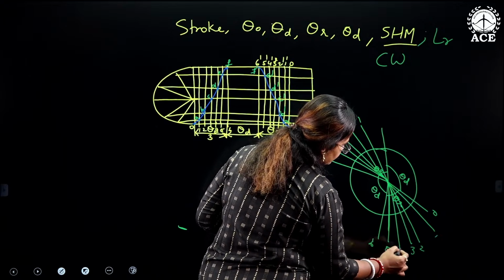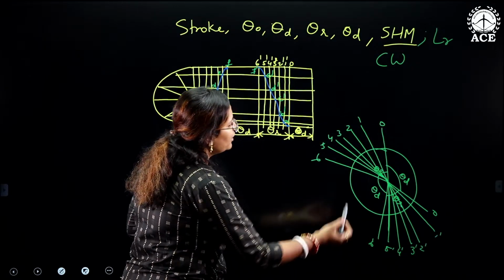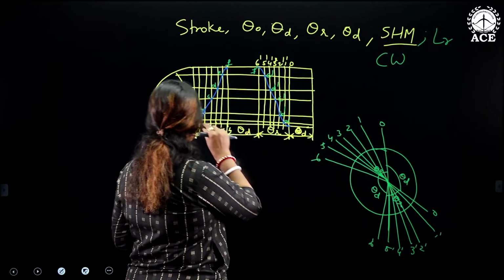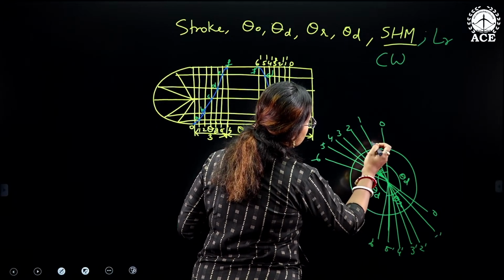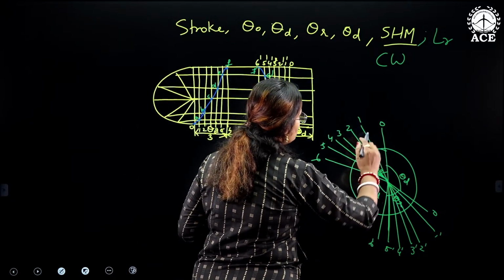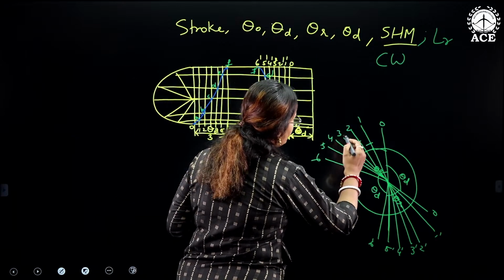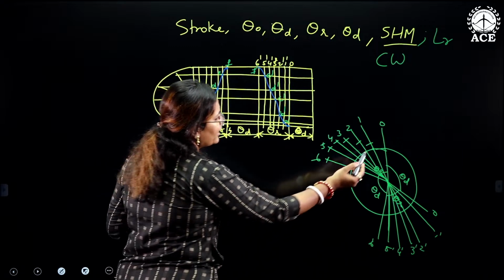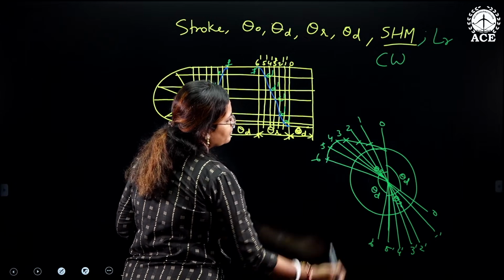So from the circumference of this least radius, measure that 1A distance and make a curve like this. Similarly 2B from the circumference over here, 3 and C you curve, then 4, 5 and 6. So you get a curve like this. Draw the curve freehand.